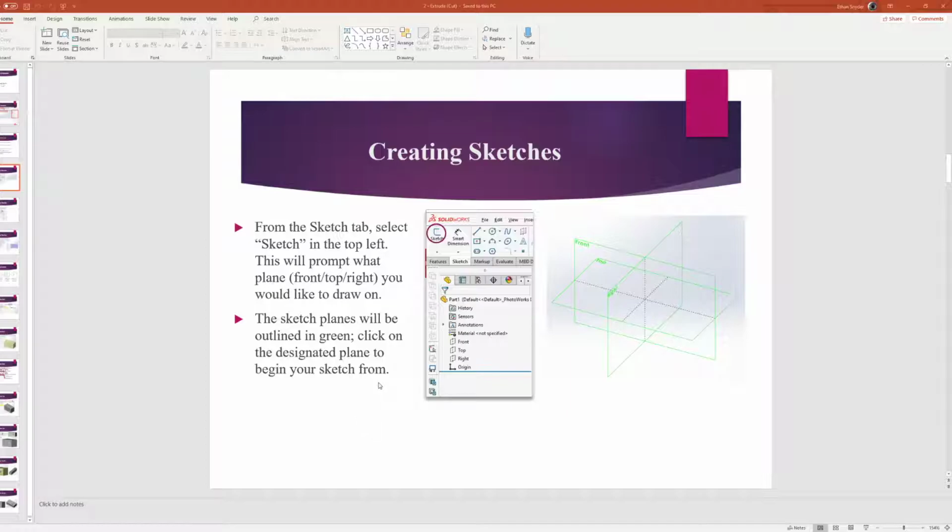Yeah, so you want to click on part first. I should have specified that. Part is going to be where you start off. So we're going to make our e-drawings from the parts. So we will always want to start off from some three-dimensional model first, and then it'll transition into some drawing, something that someone else can replicate. So yep, select the part, and then from there you'll be able to get to just your graphic interface.